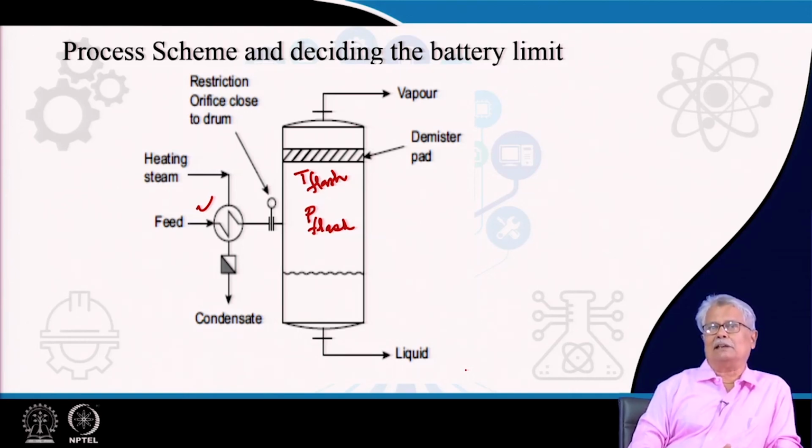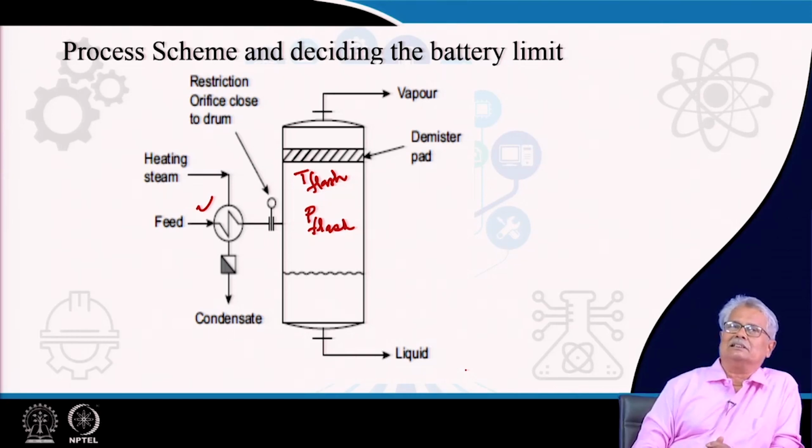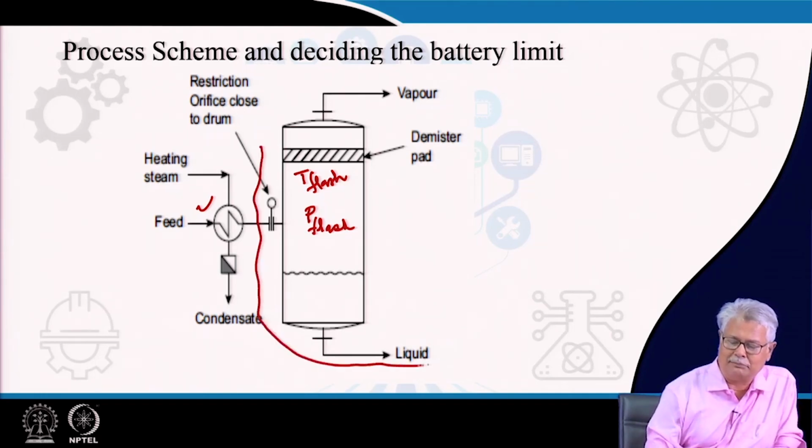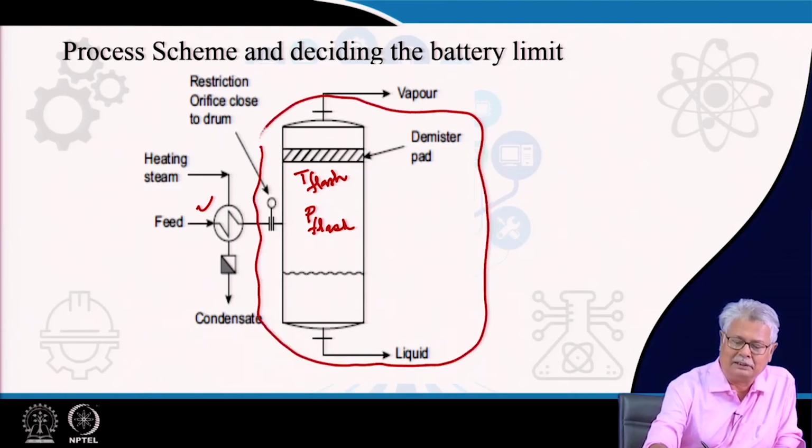Now, at this point what I would like to point out is it is absolutely important, before any design, to decide on the battery limit. That means, what are the connections to the external world of the section that you are going to design. So, I am going to draw it here and define my battery limit as this.